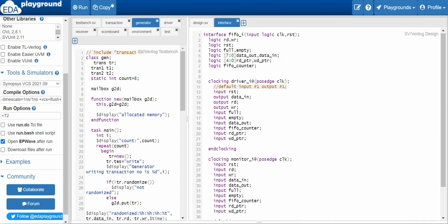Wire and reg data types. So logic is used to declare both. When we use wire and reg during initialization or inputs declaration, we get mismatches and race conditions.